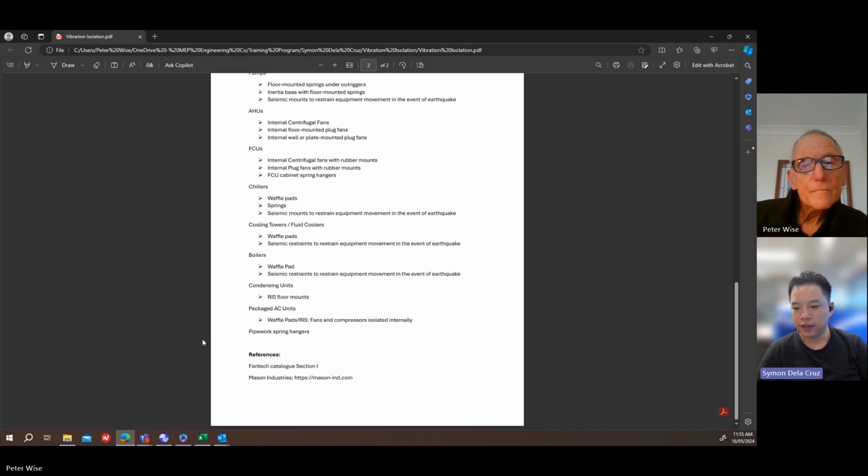We have one project now where he's rushing to finish the drawings so that he could go to the system equipment. Oh well, I don't think you need to worry about the detail of the vibration isolation, but be aware of it, or note on the drawings where it is required. Generally for fans and pumps and all those things, you will indicate that vibration isolation is required.